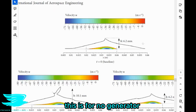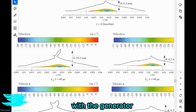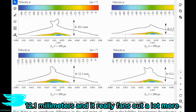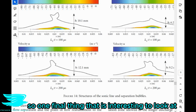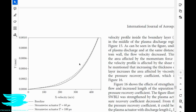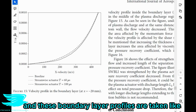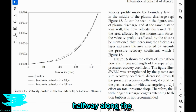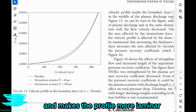So we can see here, this is for no generator. The height of this region is about 6.2 millimeters. With the generator, it goes up to about 12.1 millimeters, and it really fans out a lot more. So one final thing that is interesting to look at is the boundary layer profile, which is the velocity of the flow as you move away from the wall. And these boundary layer profiles are taken like halfway along the plasma generators. And the plasma actually reduces the velocity in the boundary layer here and makes the profile more laminar.